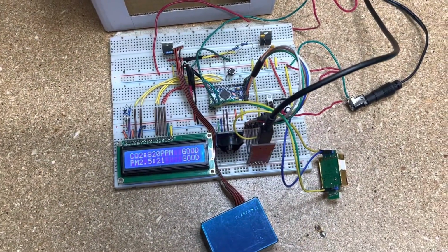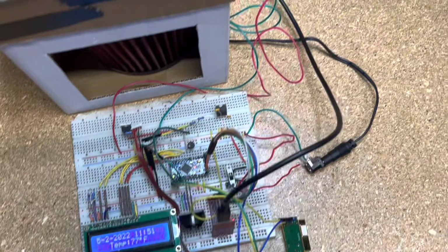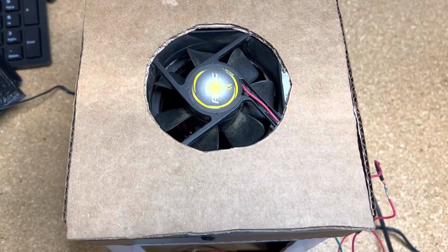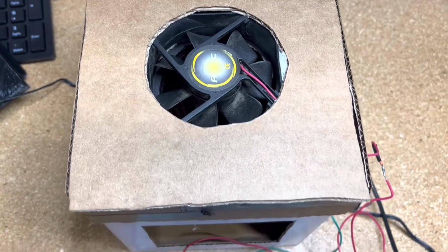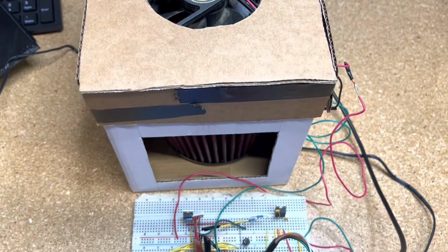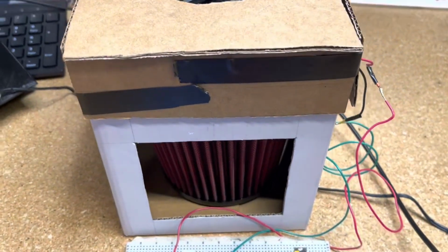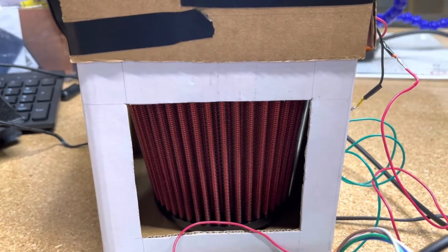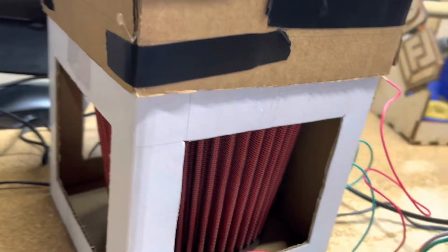Aliza was mainly involved with coding the MHZ19 carbon dioxide sensor and real-time clock module to store and display carbon dioxide maximum values for the past week. She was also involved in implementing the MOSFET voltage control for the filter's fan so that we could control the 12-volt fan with the Arduino's 5-volt output.